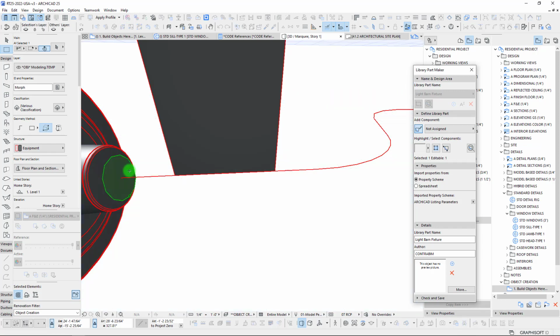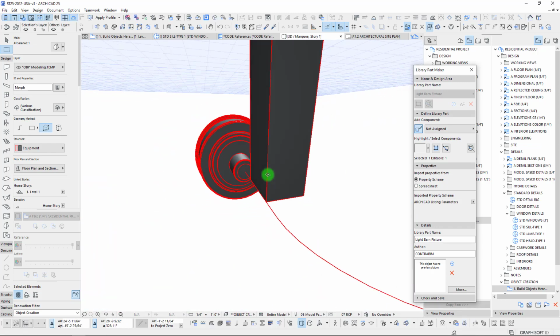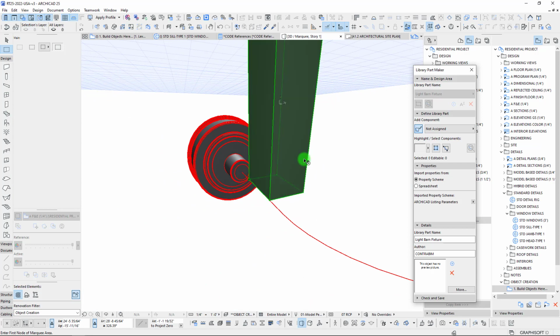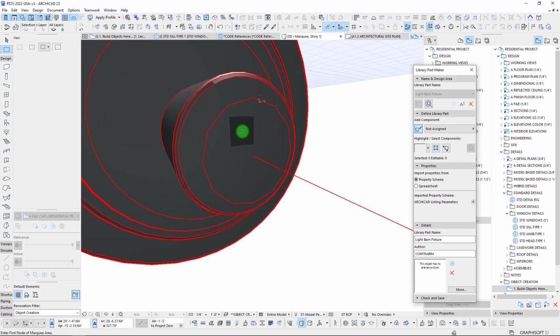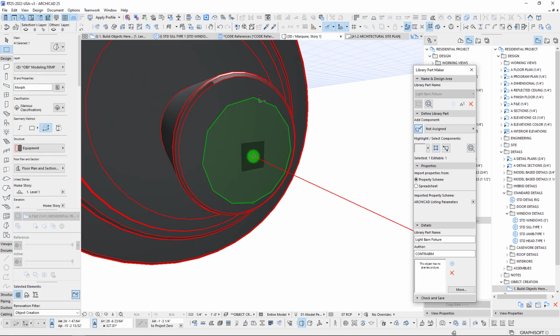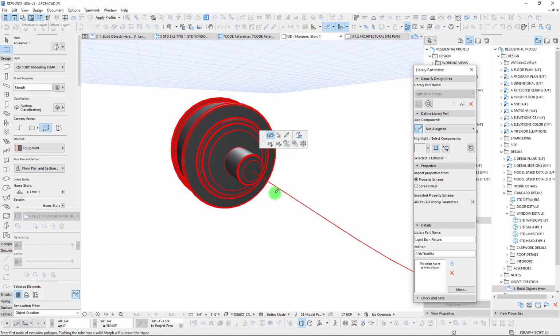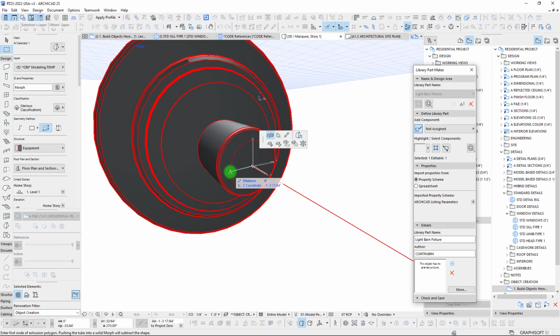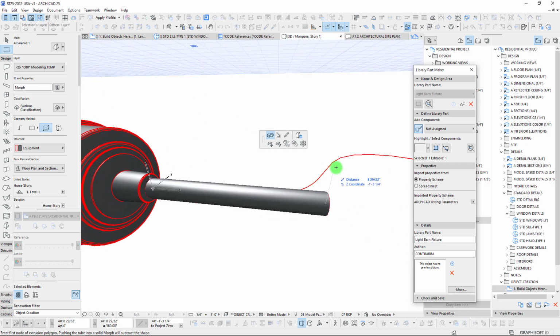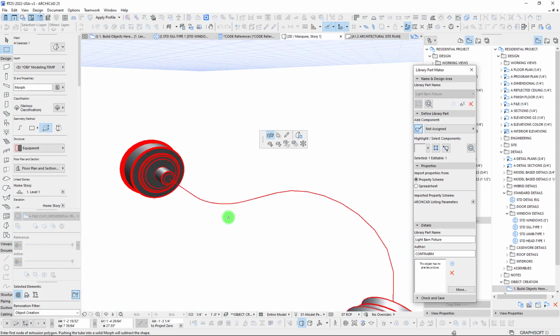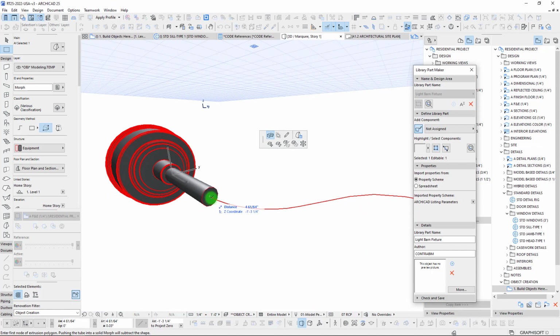Or pretty close to. We can always extrude that end there later on. But yeah, now is the time that we can take this, and when we go to extrude this, it's really important that we are clicking on our center point there to begin this extrusion, because that's the point. You can see that little black dot there that's right on this line. That's the point that we want to be extruding from, not from any point on the edge or the side, because that would get us off when we come to actually trying to create this kind of rotated shape here.